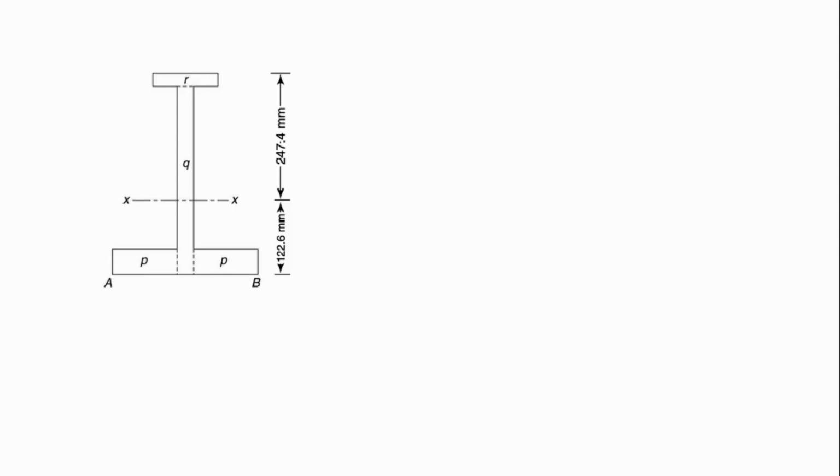We are now trying to find the moment of inertia along AB. So, we're not going to take the 1, 2, 3 designation we used before. We're going to ensure that the maximum number of sections touch the AB axis.